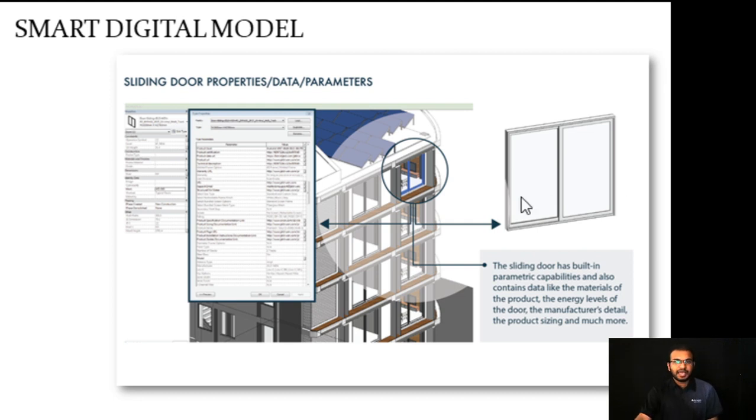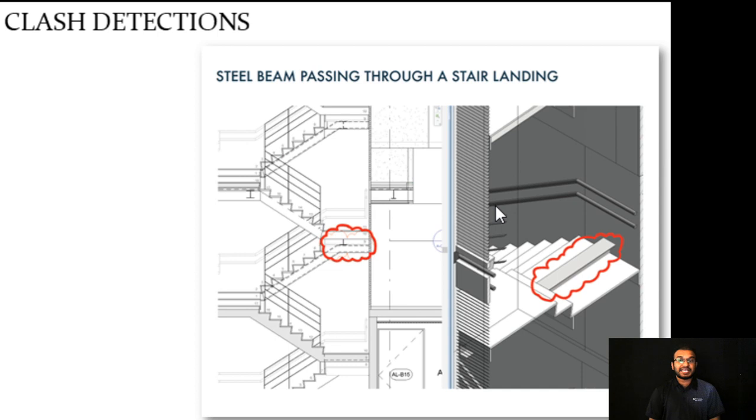And then what you can see is clashes. This is one of the major headaches for everyone. There can be different kinds of clashes in different disciplines, and different sub-disciplines as well. So what we need to understand is that when you are submitting your model or your drawings for site execution, it should be completely clash free. And for that purpose, Revit will help you a lot.